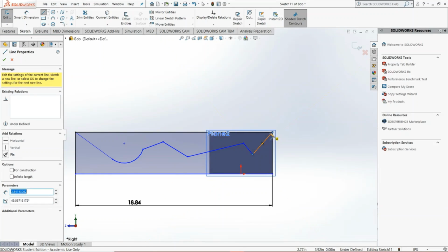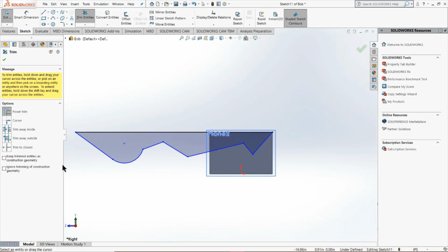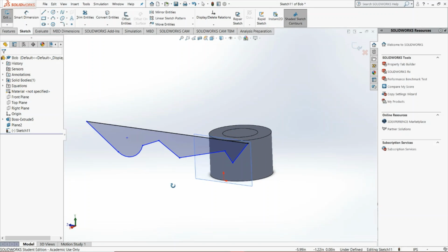And that should be adequate. That is fine. Now, I'm going to trim half of the contours, and you'll see why. Essentially, the wrap tool, what it does is it wraps this design around, if you can imagine. It wraps it all around the edge of this cylinder, and the side that's enclosed is the side that will stay. Anything below this particular wrap design here will be deleted.